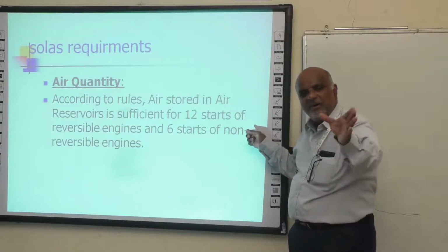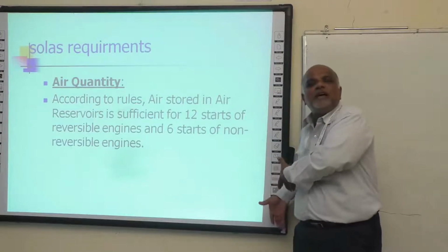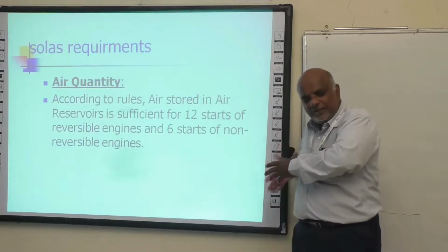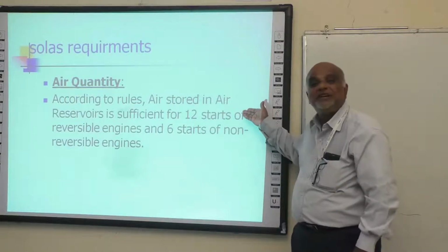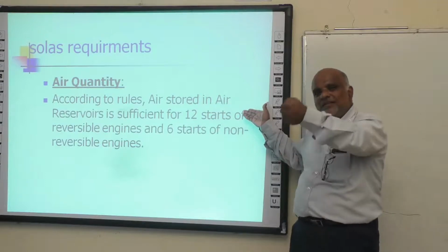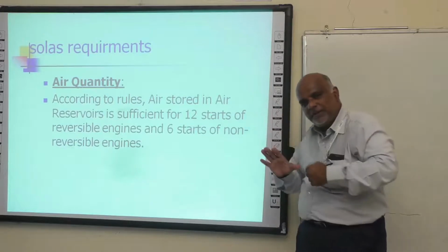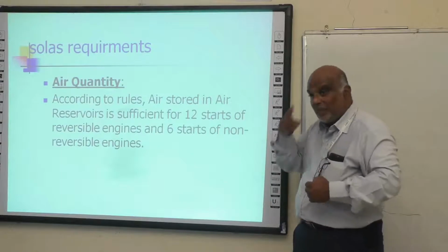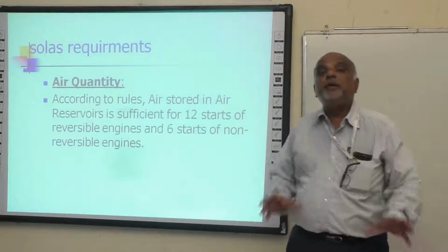Yes. Our slow-speed engine, which is directly coupled to the propeller shaft, with the propeller fitted direct, is the reversible engine, which can be reversed. You can stop, you can run it in the ahead direction, then bring it to a stop, and once the propeller comes to a standstill, you can run it in the astern direction. Now, a non-reversible engine is where a CPP, controllable pitch propeller, is there.